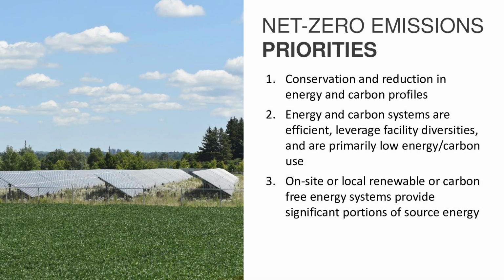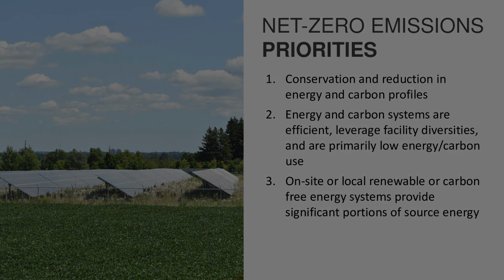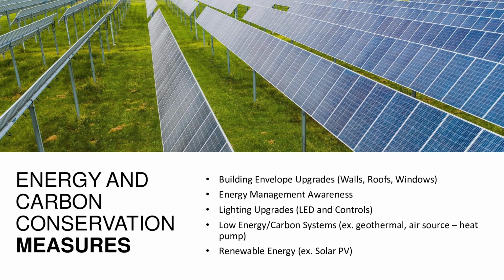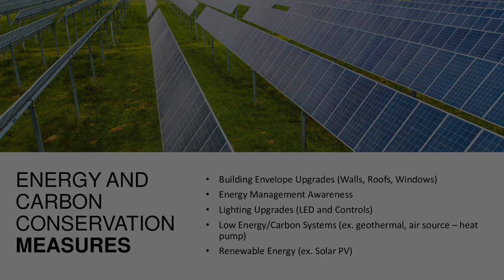This one I touched on earlier, talking about the priorities around reducing, so I'll keep moving there. Some typical measures that we might look at are listed here. So building envelope measures, so you can consider upgrades of insulation on your walls and roofs. If you're doing something like a renovation in one of those spaces, that's a great time to include one of these measures in particular. If you have to re-roof your home at a certain time, that's a great time to look at the whole roofing assembly as well, beyond just replacing shingles.